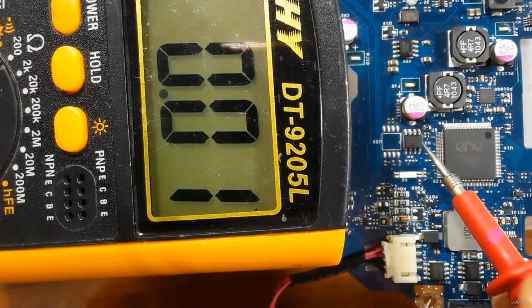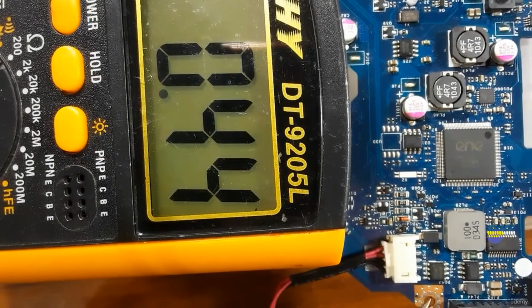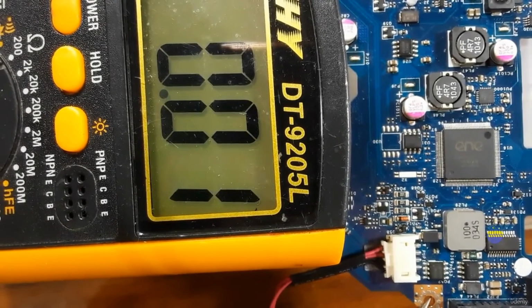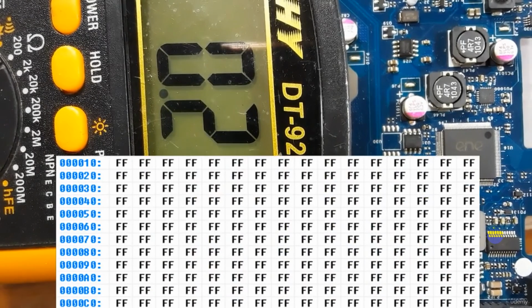So if you find that 3.3 volt in pin number 8 of the BIOS, but the laptop still does not work, means you should reprogram the BIOS, because about 90% the file or the firmware inside the BIOS is corrupted.